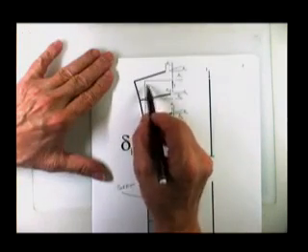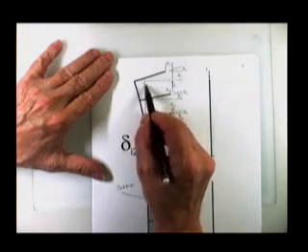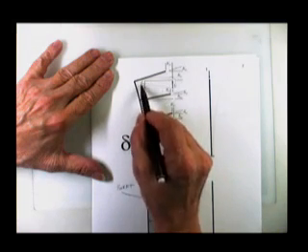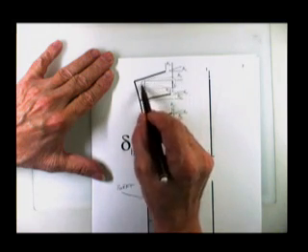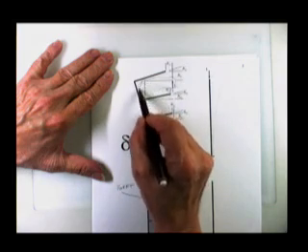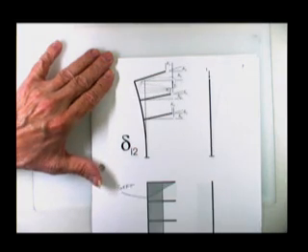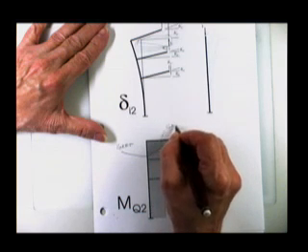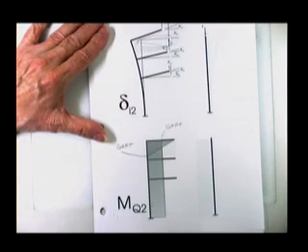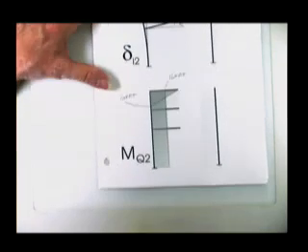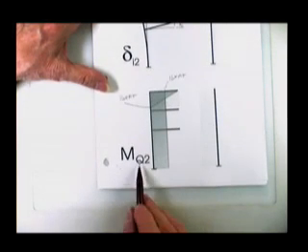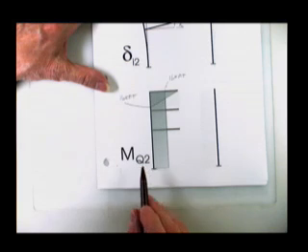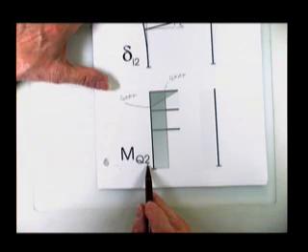And when you turn the corner, that's 1 times 16, 1 times 16, 1 times 16, 1 times 16, and therefore it stays 16 kip feet, and it's plotted on the tension side. That is the moment due to the unit loads, where a unit load has been applied to the structure in the number 2 direction.